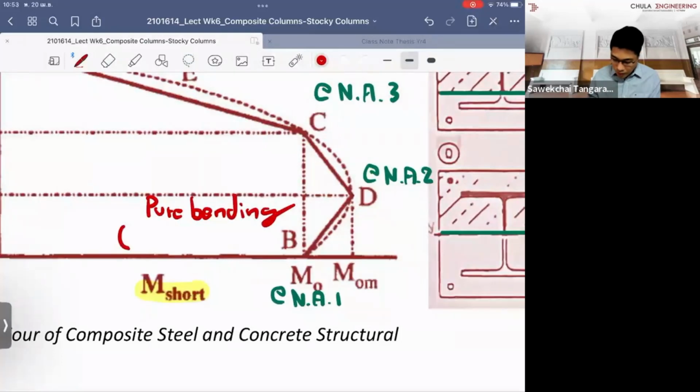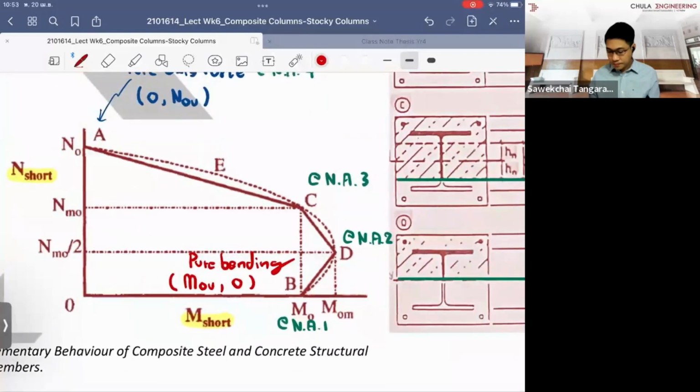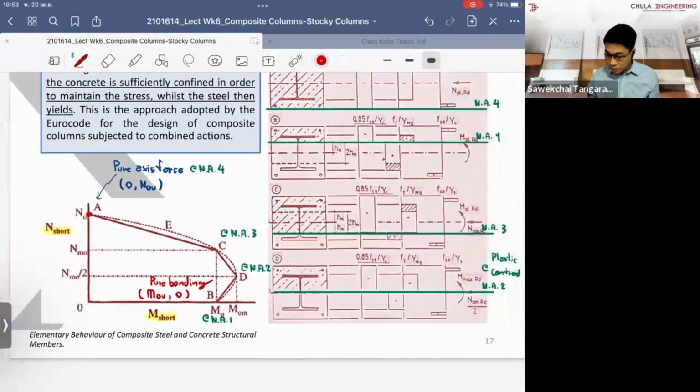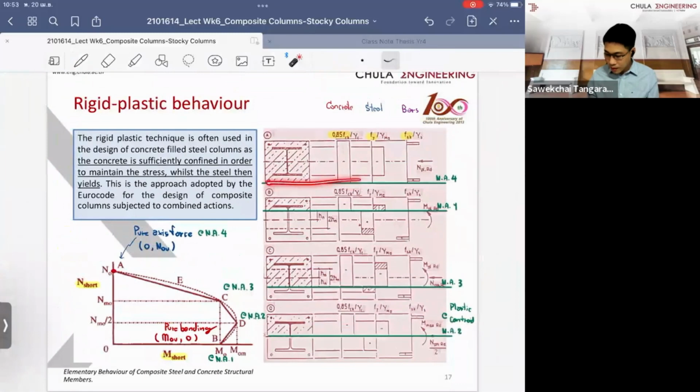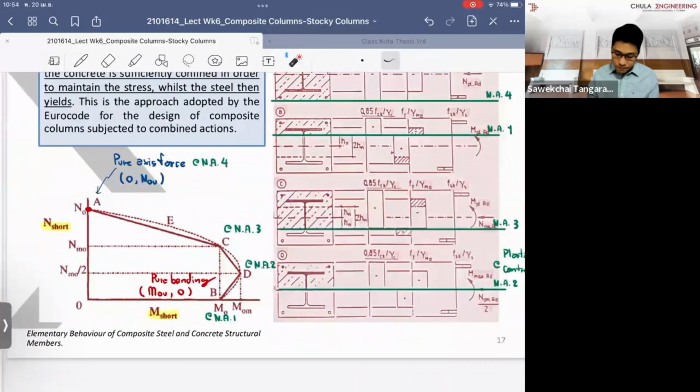When you plot the graph, you have the M, which is the ultimate strength. So we have a couple of points. Sorry, it didn't go in order. At the bottom, you raise it up to some level and you get the point here; you raise it to the plastic centroid, you have the point here; and you go up to the pure bending, you have the bottom point.